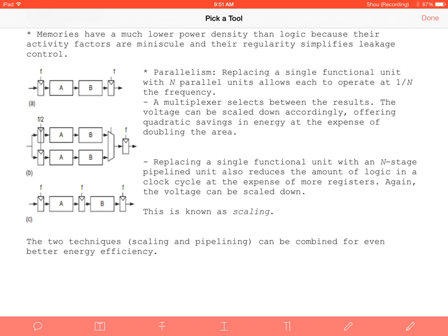So the trade-off in power becomes reduced because the frequency is going to be a little lower. So you have the same amount of area, but a slightly lower frequency. So there are trade-offs there for each of those. But the big benefit, especially when you're cutting the frequency in half versus gaining half the area, is that you significantly reduced your power consumption.